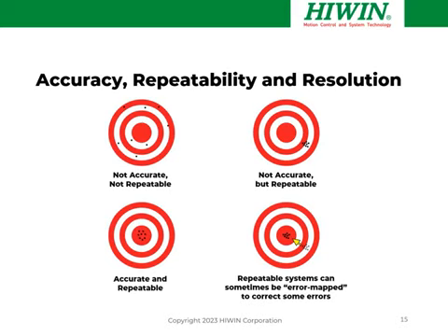Don't assume that a high-resolution motion system also means it's accurate. In terms of cost, accuracy is the most expensive parameter to achieve. Resolution is often the least expensive. Resolution is simply the smallest increment of information in the system.